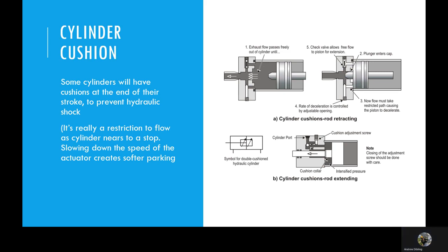So if I push the joystick and keep it fully extended, the pressure won't continually act upon that plunger. It will be relieved through the check valves. Sometimes they're just literally rubber stoppers or screws, or springs that prevent the cylinder from smashing up against its end of travel.